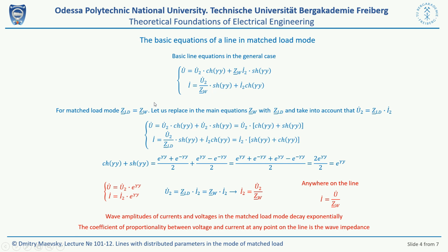In the case of matched load, the wave impedance of the line and its load impedance are the same. Therefore, we replace the wave impedance with the load impedance in these equations.